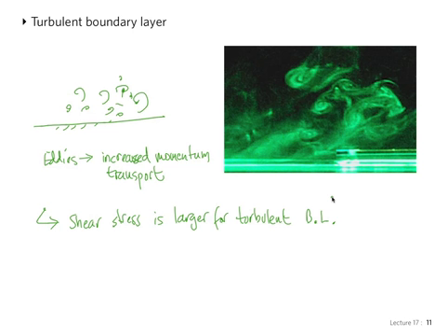So then a plate moving through a turbulent liquid would be much more resistant than one moving through a laminar flow. The drag is going to increase when the boundary layer becomes turbulent. There's more transfer of momentum. Therefore, the fluid adjusts between the free stream and the no slip boundary layer much more quickly. The velocity gradients are much more pronounced, and the shear stress is also larger. In general, those are the physical description of the boundary layer.